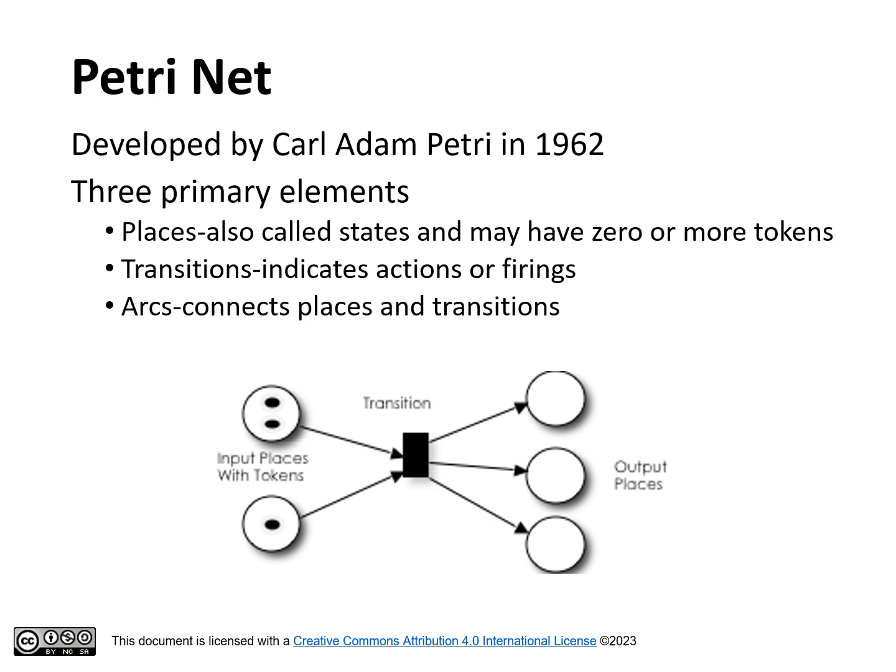In the Petri net shown in the figure, the 2 input places have 2 tokens and 1 token respectively. The tokens are moved from the input places to the output places when the transition is enabled or fired. The number of tokens that are moved from input to output will depend on the capacity of each arc, which is indicated as weight.